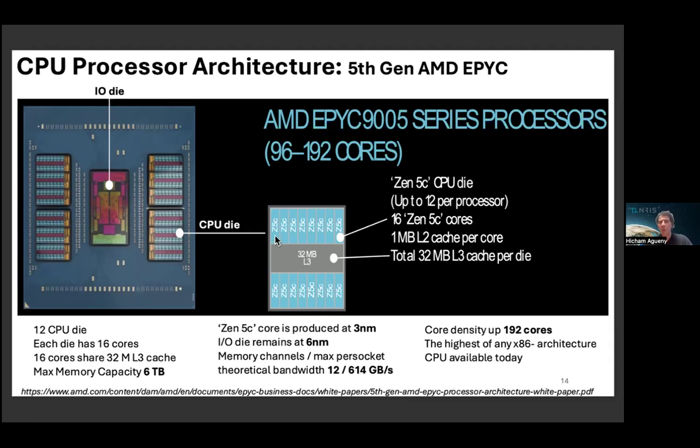And of course, each core has its private L2 cache memory of 1 megabyte of capacity. This is very important. Understanding the memory hierarchy of a system is also very important in terms of optimization. As we know, accessing the cache memory is faster than accessing the main memory, meaning that if an application is well optimized to make use of the cache memory, it will improve the communication and reduce the communication latency.